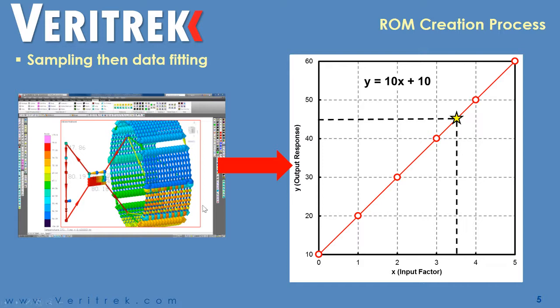One, you could go back to the existing thermal desktop model. You could put a power value of 3.5 into that and wait for the simulation to run and track the output response, and you'd find that you would have a temperature of 45. The other thing you could do is simply put 3.5 into the equation that we've developed, and you can more quickly come to the answer.